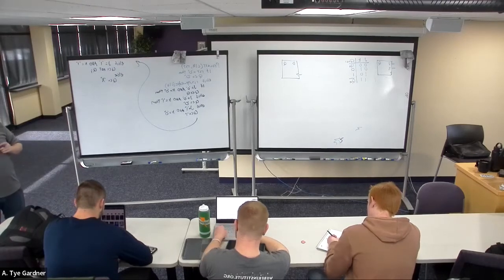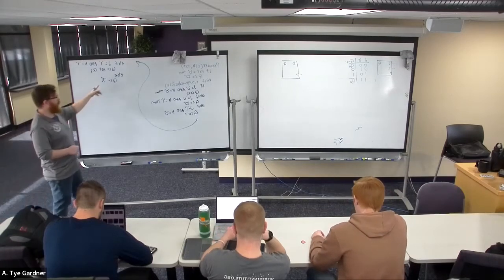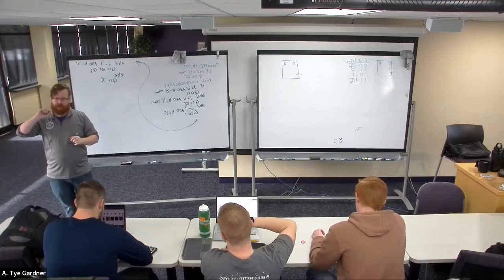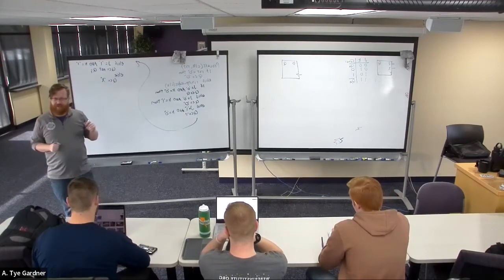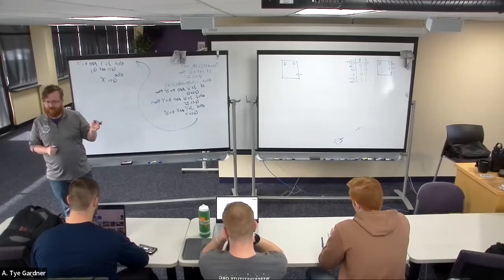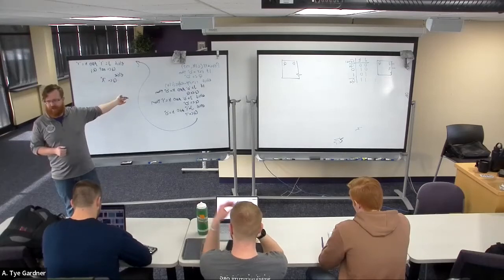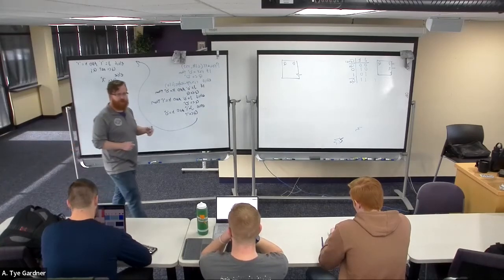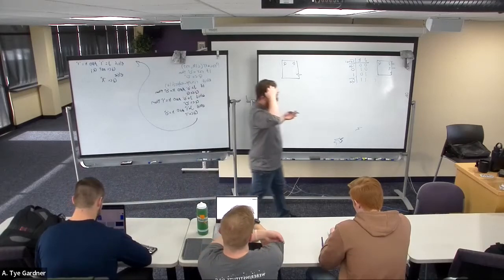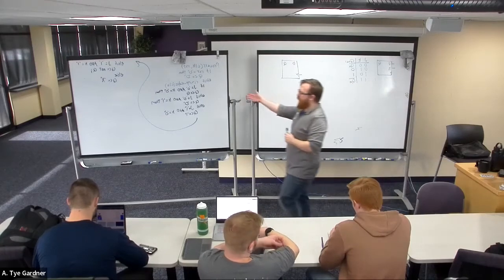Normally in our test bench, if we see an X, it usually means dual driven, meaning there's one signal that we're trying to tell to be 2 different values. So that's the one downside of X, that you're not quite sure why it's an X. It could be dual driven or it could be this case. It's still really easy to check to go see if it's just bad inputs. So I prefer X. You could use some of the other values. You could use U. I would not use Z. Z has some other issues that we'll talk about later. But it's just a sign to say, well, I want to handle all the other cases.